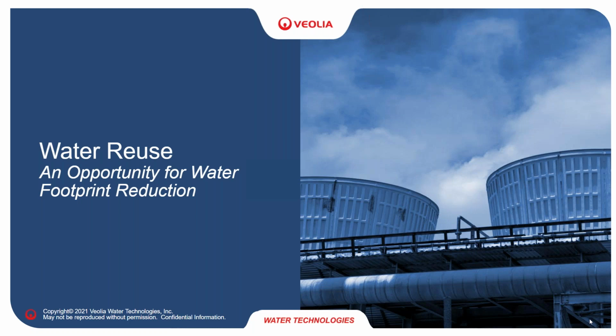So let's switch gears a little bit to address something that we see happening more and more these days. As reliable sources of fresh water become harder to find and more expensive to obtain, sometimes a solution can be found within the property lines of your site by simply looking for water streams that can be reclaimed or recycled before leaving the facility. And since one of the largest water using processes in many industrial facilities are the cooling systems, many of our customers are taking reclaimed or recycled water back into the plant and using it as cooling tower makeup. While this can have a positive impact on your overall water footprint and look environmentally or socially acceptable, it might not be as straightforward as you think.